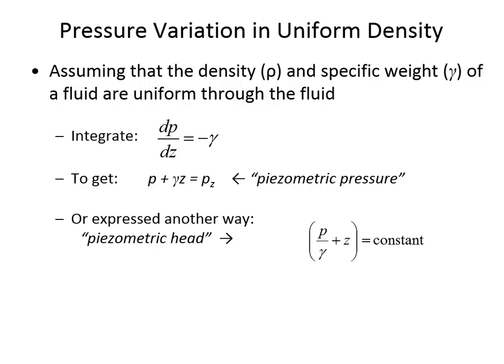Anywhere in a static fluid, the piezometric head and the piezometric pressure are constant. When the water starts moving, it's not constant, but as long as you've got hydrostatic conditions, this hydrostatic equation can tell you how pressure changes between 2 points.